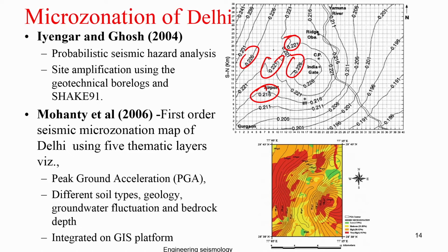Then Mohanty carried out a complete microzonation study and tried to estimate the H/V ratio. There are some geologists and seismologists who believe that doing a microtremor study and mapping a predominant frequency is called microzonation. But as I told you, the predominant frequency will help you only to give the fundamental frequency of your soil column. This is basically related to the thickness of the soil column.